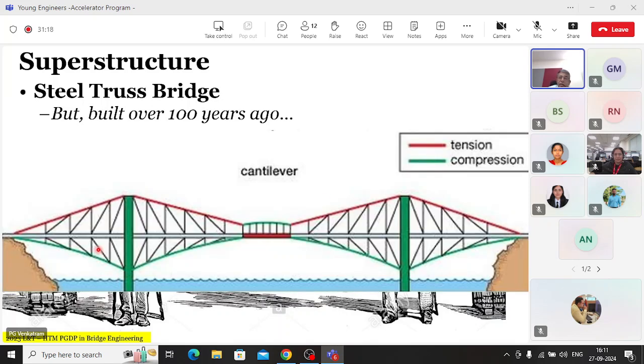The way this operates, you have to understand all of it in the form of tension and compression. You have the tension being provided by the hands of the man, and the compression provided by the rods and the suspended span. You have a beam bending behavior, with compression at the top and tension at the bottom. So this is the simplification of the same thing in a very beautiful and elegantly put sketch: two people can carry a full man's weight.